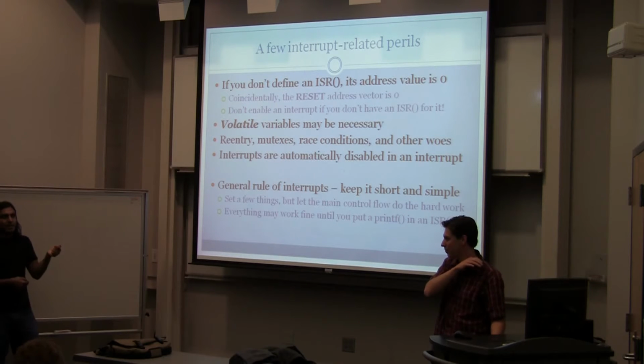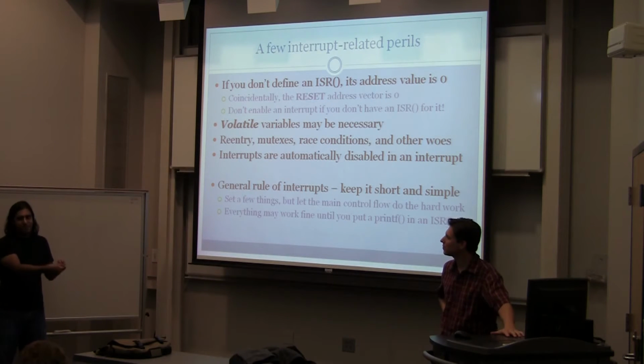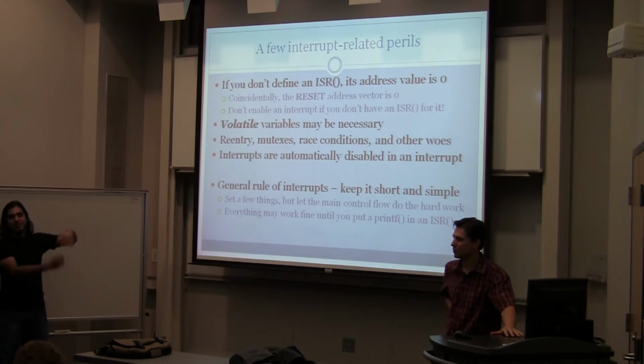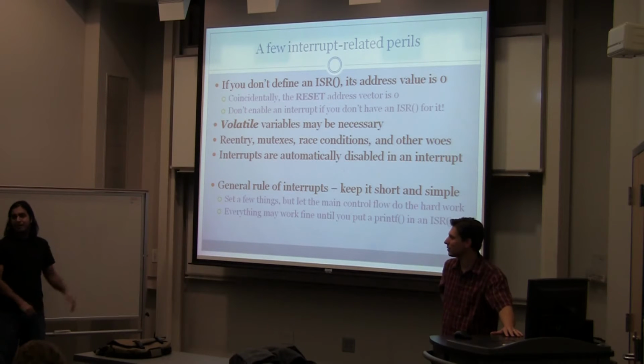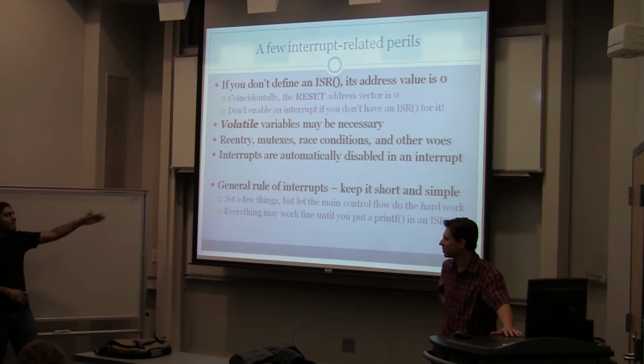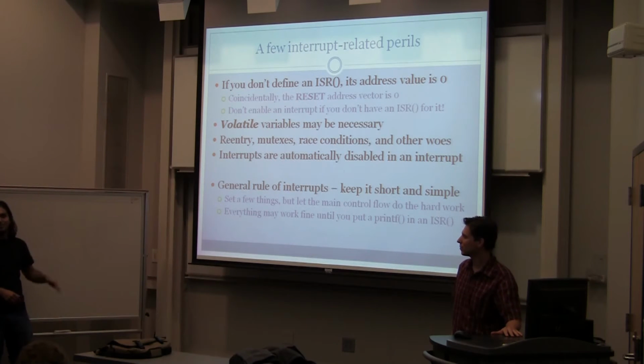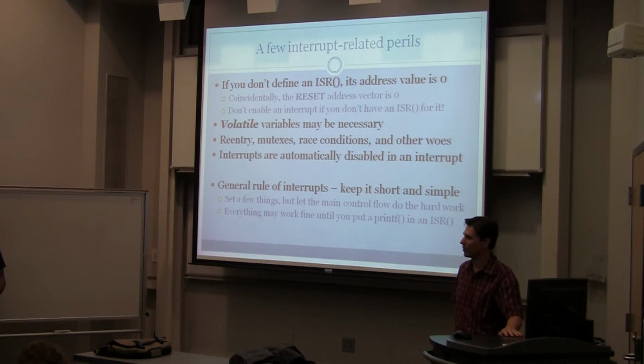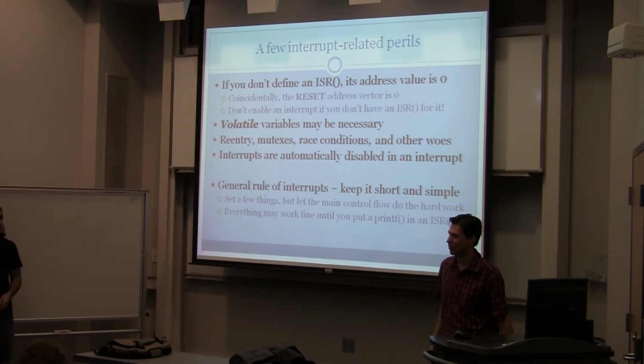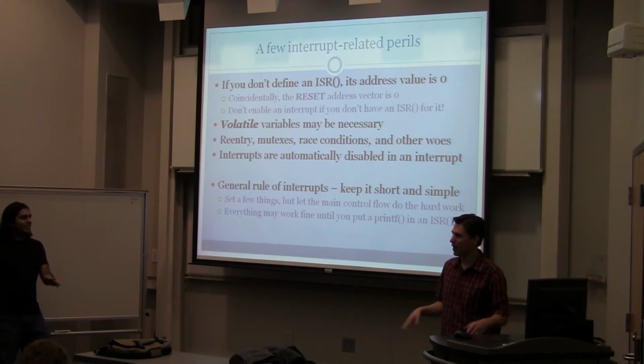And keep in mind that you can usually set some sort of variable which then will tell your main code to go do something which will take a long time later. That's usually what you want, because if an interrupt's running, it's usually screwing up other stuff that could be running at that time. So the most you would put in an interrupt is like 3 or 4 if statements, because those are evaluated pretty quickly.